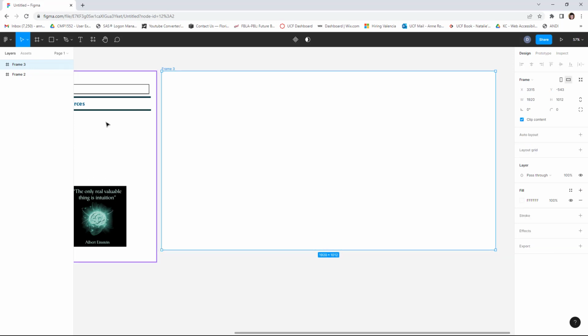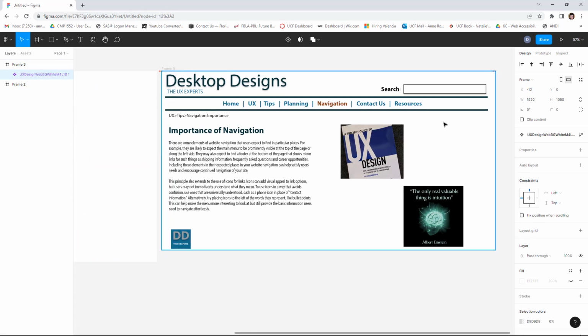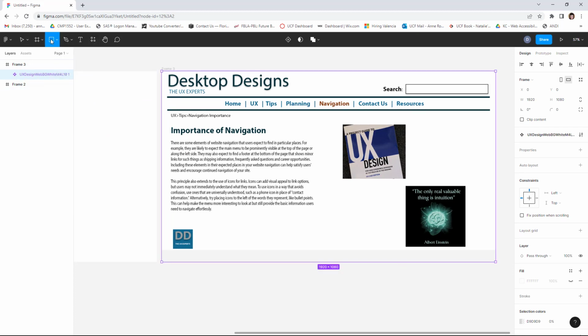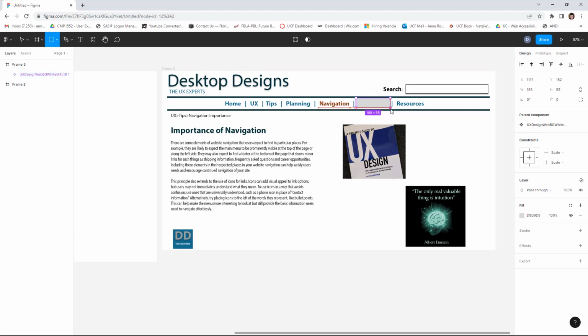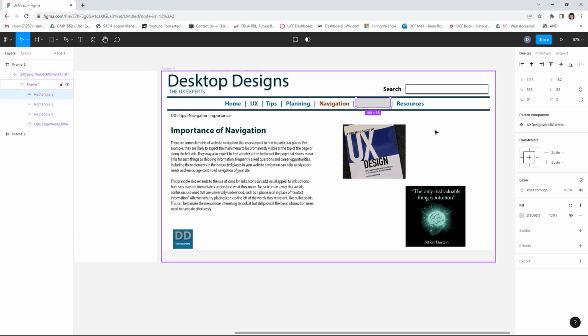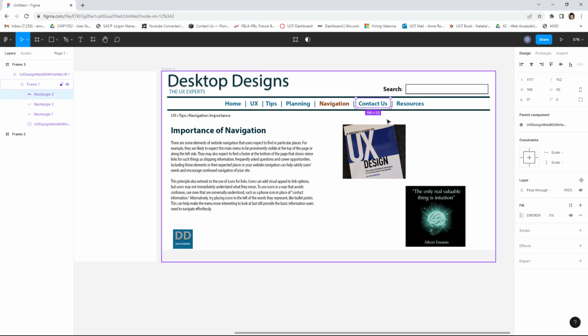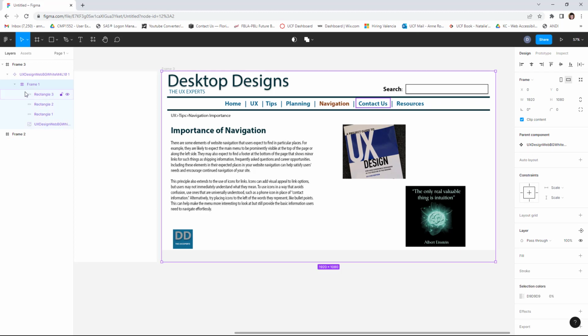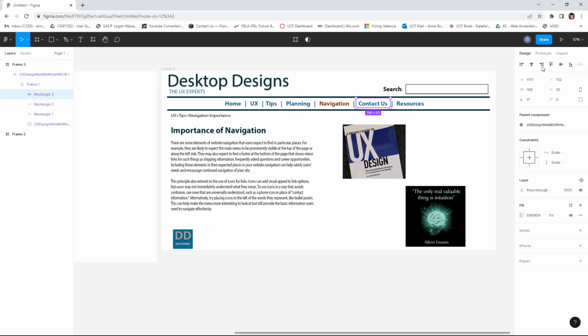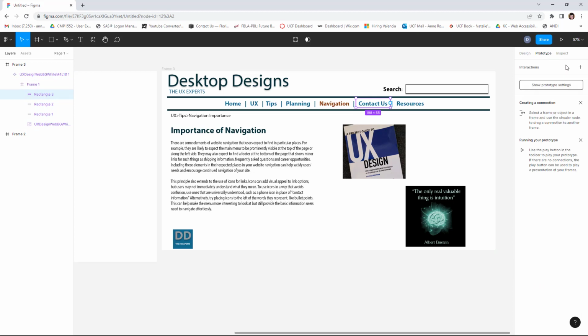At the top right, I choose the rectangle tool and draw a rectangle over Contact Us, but to see the menu text, I'll need to make the rectangle transparent. Then, in the properties on the right, I need to reduce the 100% fill to 0% fill, thus creating complete transparency. Next, I need to change the view to prototype. I must click the plus next to interactions. First, I select a behavior. Here, we'll click on click.